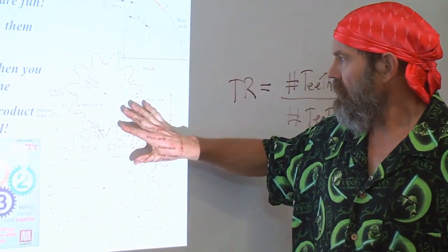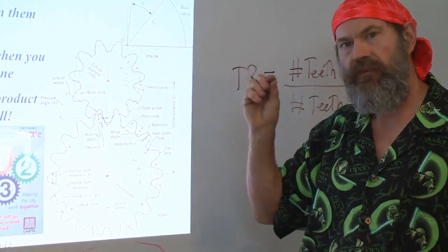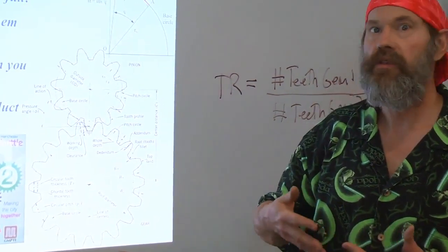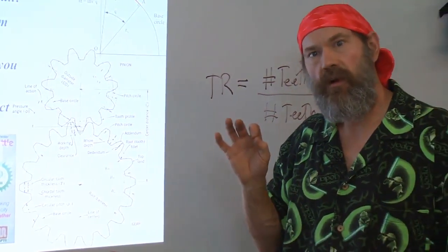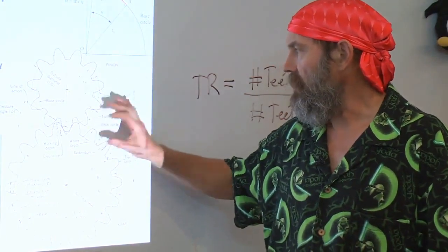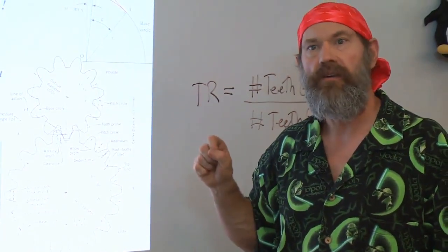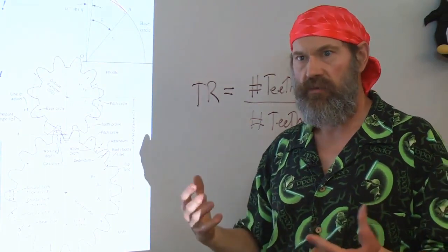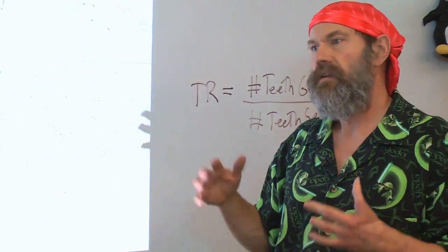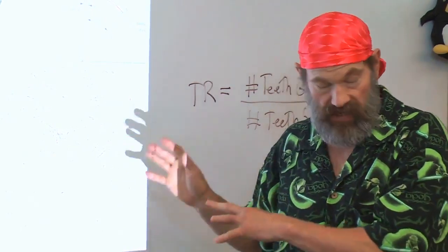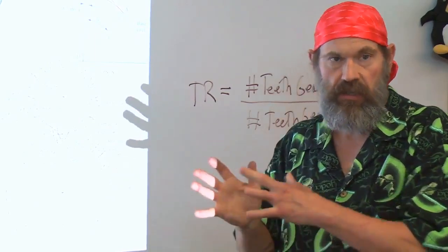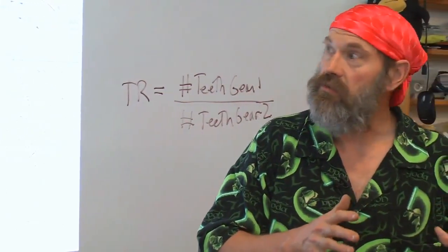So the smaller the pressure angle or the finer the teeth are, the less separation force and the quieter the gear train tends to run. But the smaller the pressure angle and the quieter they run, the smaller the teeth are, and the individual load that a tooth can bear is less. So you use a large pressure angle to get a large tooth to transmit a lot of torque, but it can tend to be more noisy. So that gives you a range of design, from very quiet gears to gears for big forces, in how you want to think of picking a pressure angle.